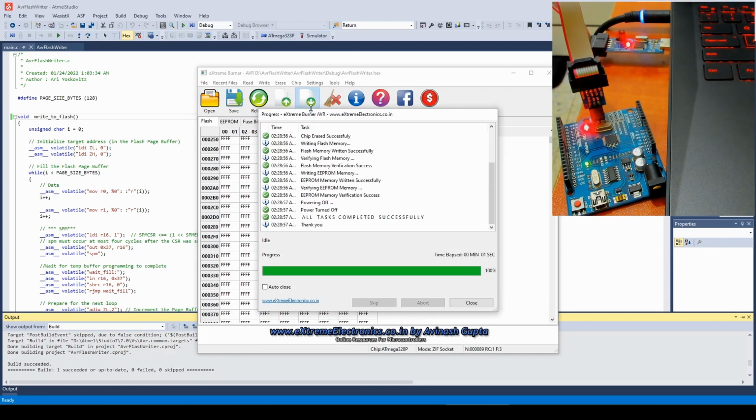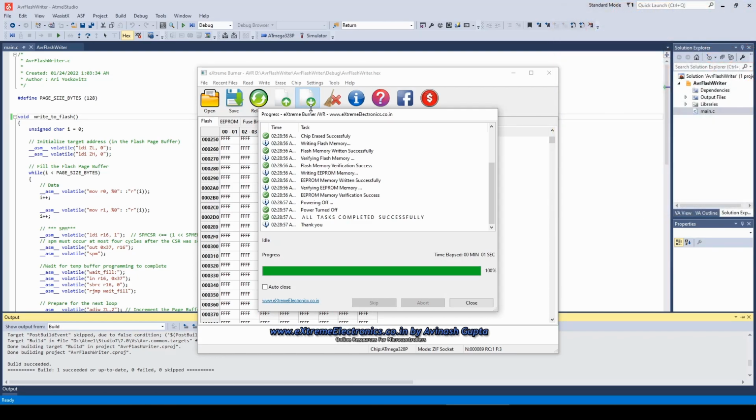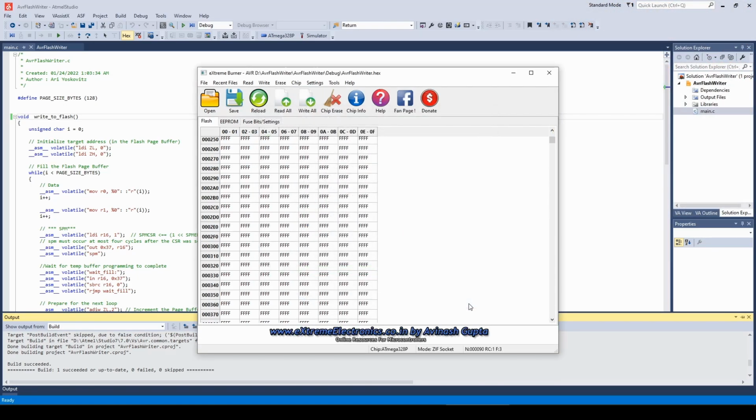Burning is really quick because only those areas that require writing are going to be burned, and our program is very small. Now, our program started running immediately after the AVR was taken out of reset, meaning right after we have burned. Therefore, when we are now going to read back from flash, we are expecting the target area to include our consequent numbers if things were about to work.